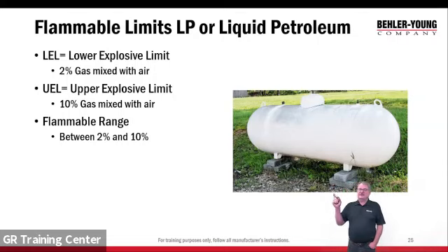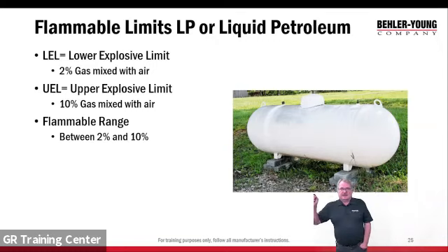All right, they only fill this tank to 80% because we've got to leave room for expansion. Believe it or not, the liquid actually boils off and vaporizes. So the top of the tank is filled with vapor, which is what we're going to use. We're going to draw the vapor off because liquid propane directly is not going to burn. We need to vaporize it first and mix it with oxygen. So we're going to draw the vapor off the tank and send that into the house.